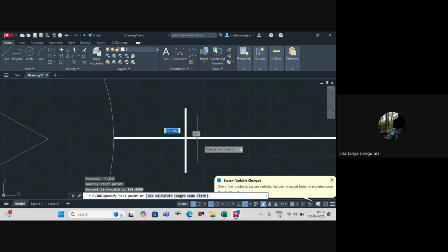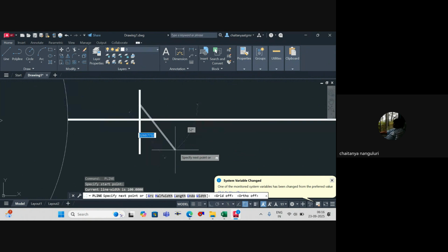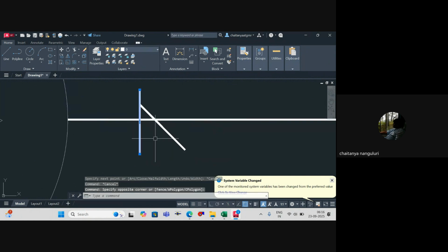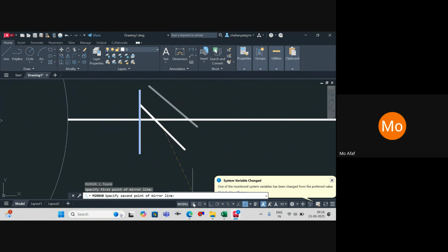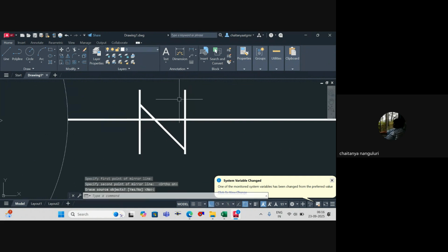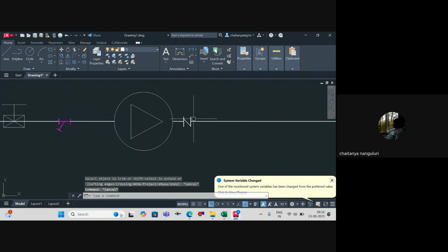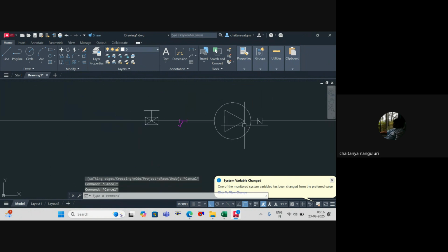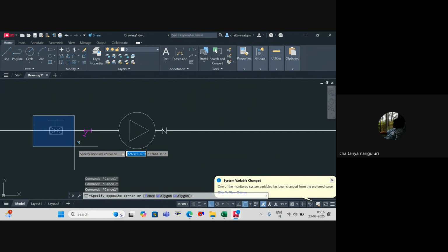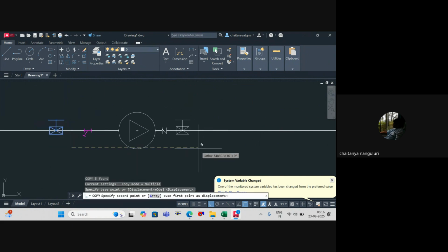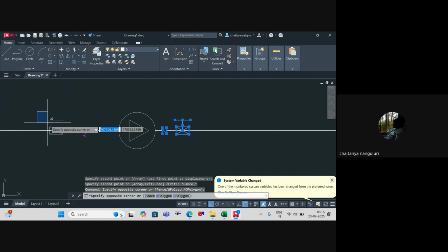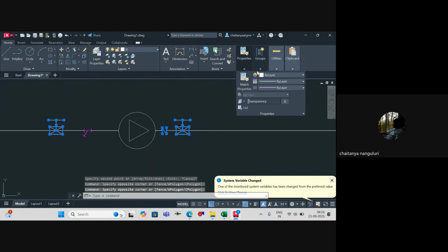For any pump, not only for HVAC, the minute you provide a pump, this assembly is constant, with respect to the type of application. This NRV allows the fluid in this direction and doesn't allow it in the opposite direction. And one more butterfly valve at this location. So these are the points that I have.